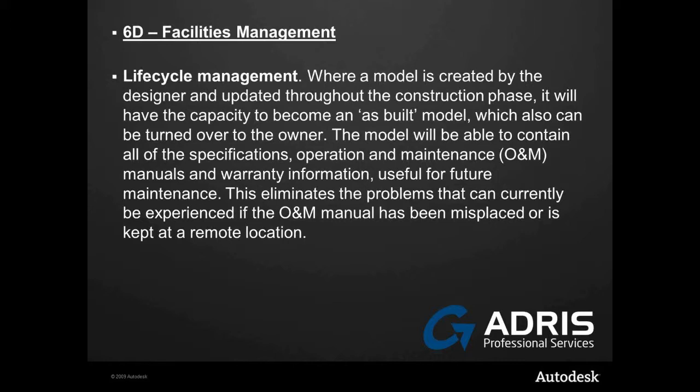we can automate it. We can extract via a wizard the lifecycle, the maintenance data associated with the model, and then extract that in the form of a spreadsheet. And there are several ways of doing that. That could be a manual process if you wanted to do it, but there are other solutions. Specifically, I'm sure you're probably coming across the term of COBie.